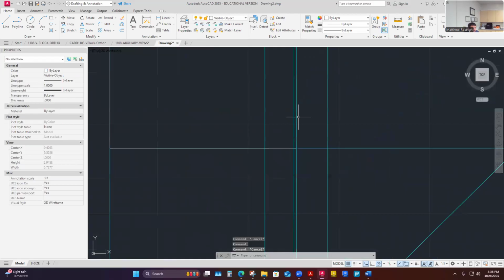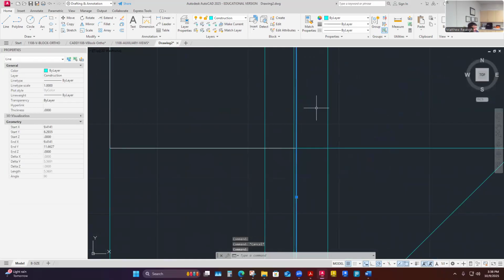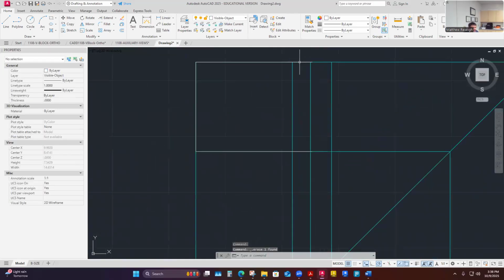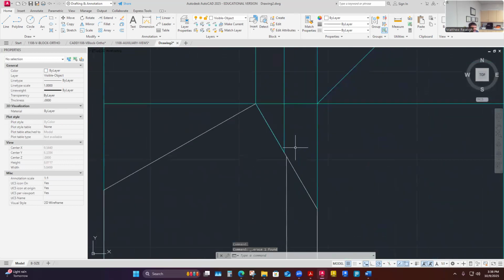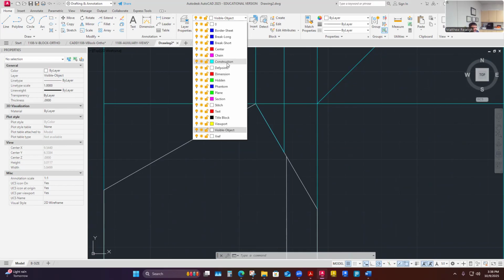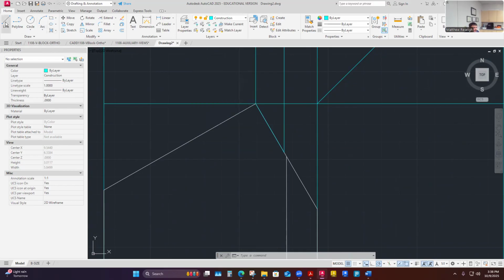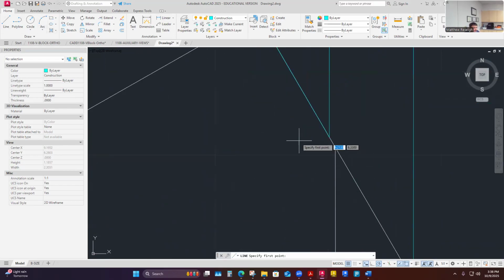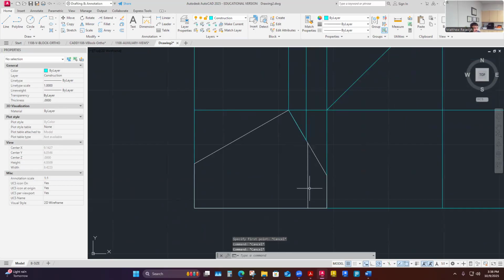what caught my eye is when I was snapping that line, it wasn't 2.57. So I just kind of wondered, did I put this projection in slightly skewed? Maybe I'll come back here and draw it. This is what I got to do. I got to check myself. Watch the dimensions that are snapping. Maybe I need to make sure that this one was truly orthographic as well.